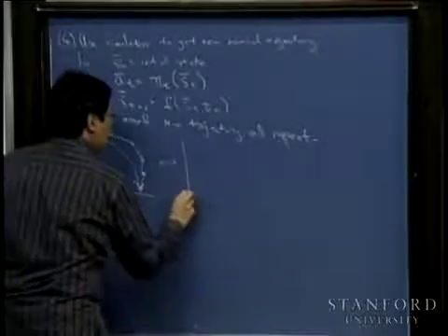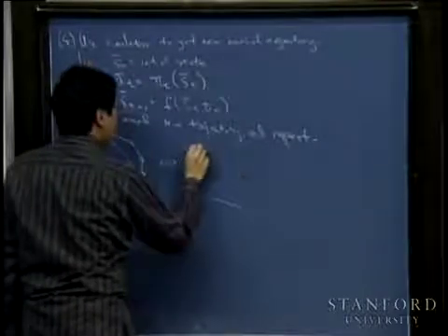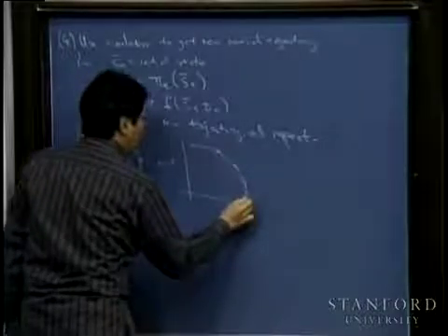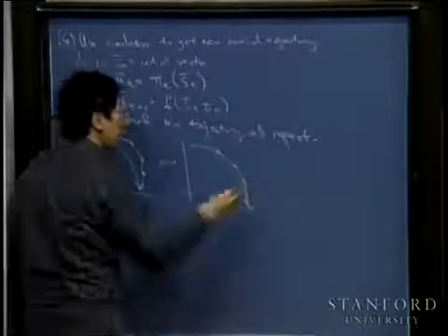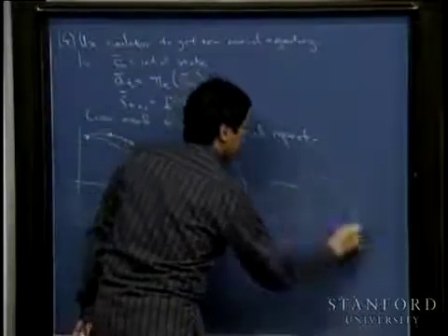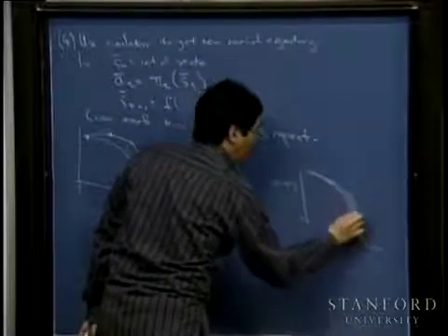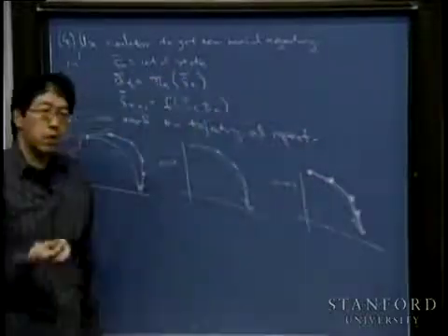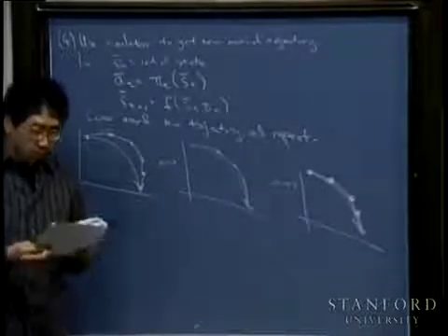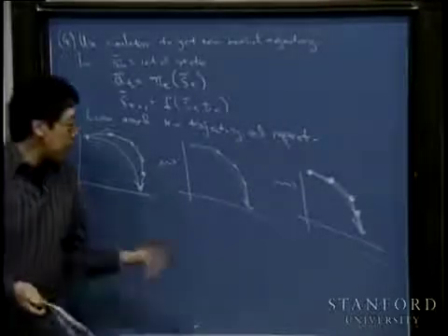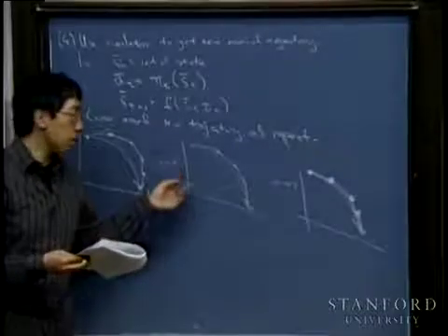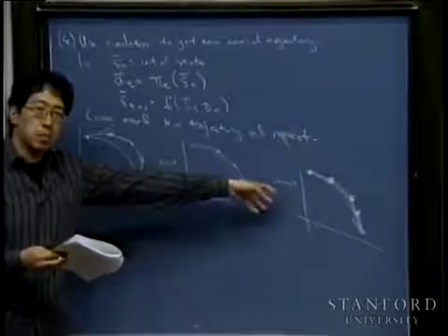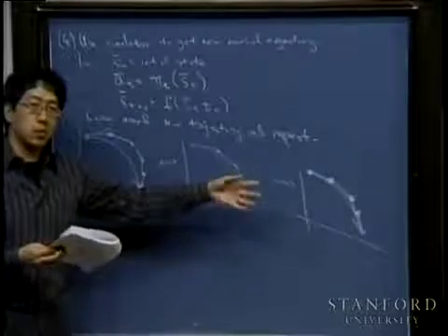And so after one iteration of DDP, if that's the target trajectory, maybe you get a little bit closer. And now you have an even better place around to linearize. And then after another iteration of DDP, you get closer and closer to finding exactly the trajectory you wanted. Okay? So DDP turns out to be a form of a local search algorithm in which on each iteration you find a slightly better place to linearize, and so you end up with a slightly better controller and you repeat.